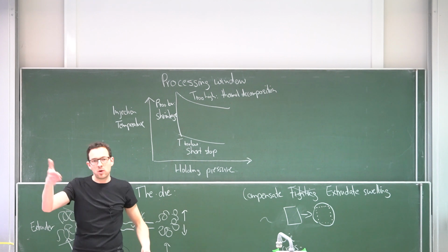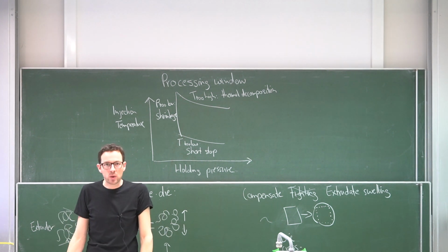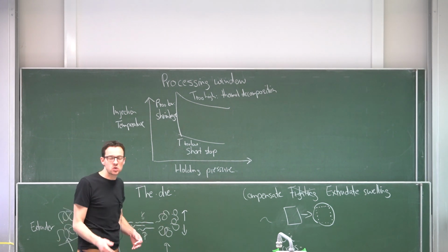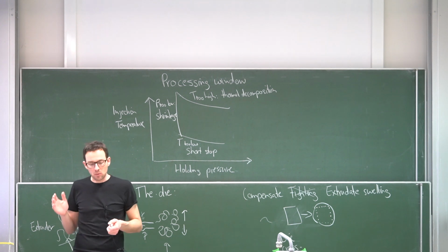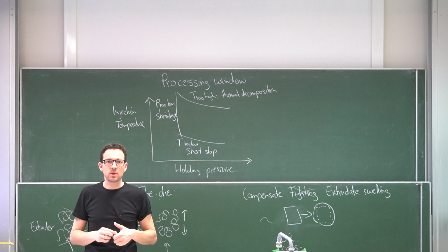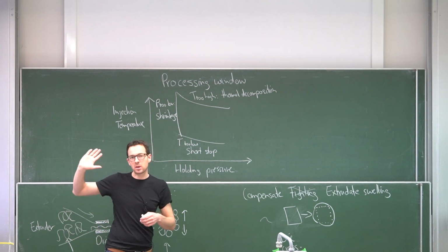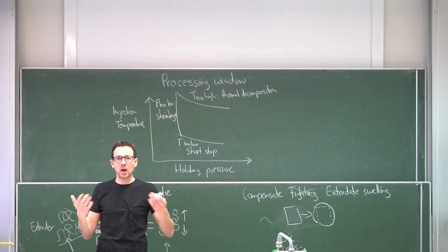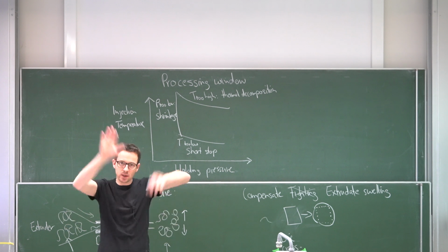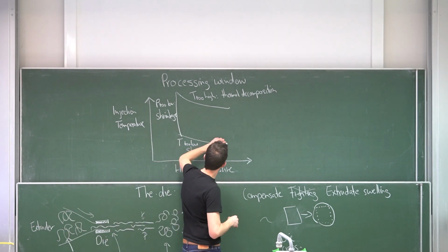And then we increase our pressure more and more, then we get our shrinkage under control, more and more following whatever specifications we may have. But if we overdo the pressure, the extruder cannot really operate functionally anymore. And then we create what is known as a flash, and that means that the polymer just pops out in an uncontrolled way. It's a little bit like a garden hose that you turn up too much, then it just sprays and starts to randomly extrude.